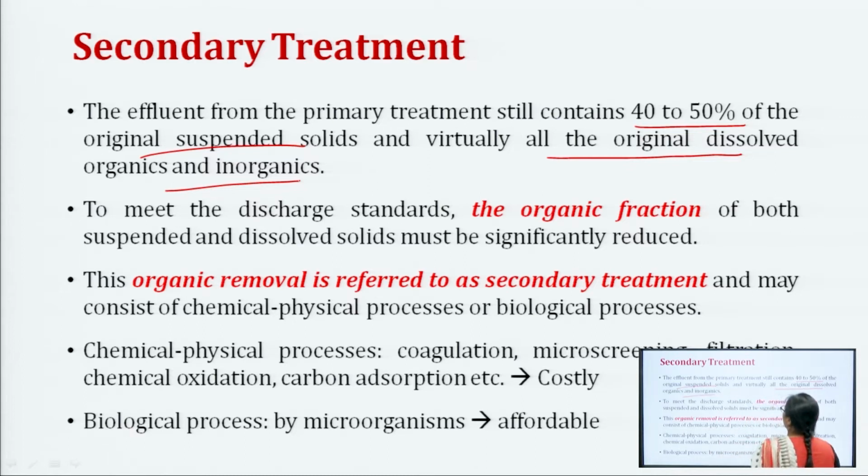And what are you going to do? To meet the discharge standards, the organic fraction of both suspended and dissolved solids must be significantly reduced, right. Inorganics were already removed by grit chambers, and primary sedimentation removed a part of the organics, right, but the majority of the organic part is still there.